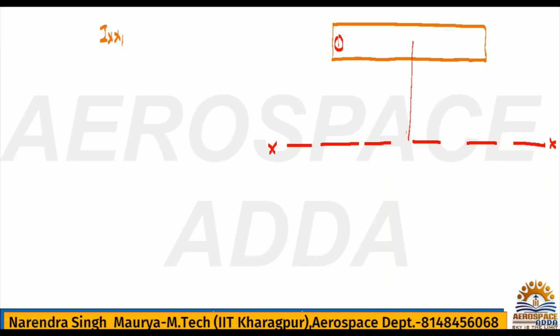Now you have to use the parallel axis theorem. I had explained, if you calculate moment of inertia for any section across the CG, this is the CG axis. Since this is a rectangular section, it's bd cube by 12.